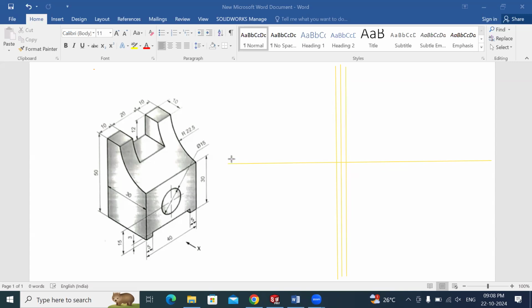Similarly, this is first line, this is second line. Finalize the views. This is the front view. So left hand side view is there, which is to be at the right of the front view. So if here there is front view, here it will be a left hand side view at the right of the front view. So starting with front view, you can start with any view.